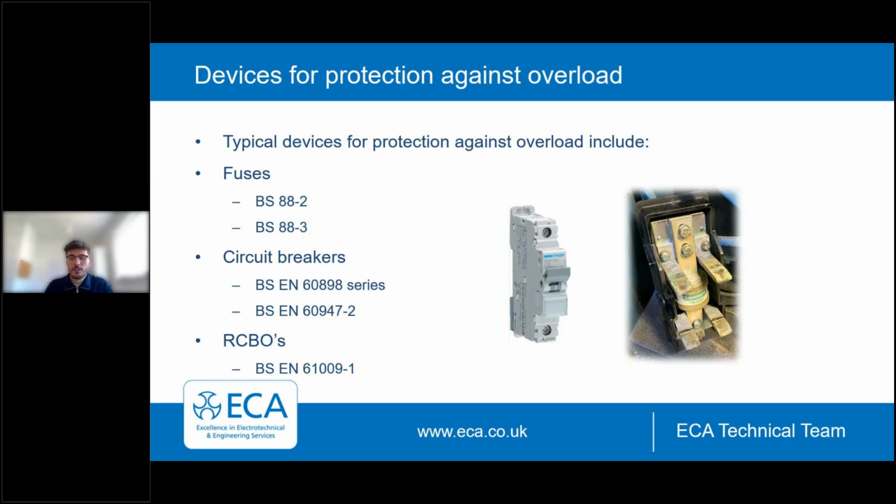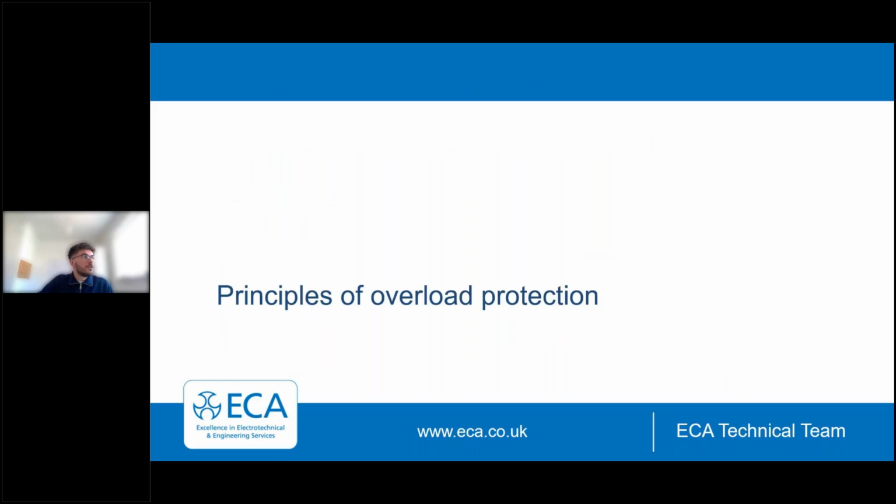Now, for some devices, particularly BS EN 60947-2 devices, some potentially being moulded case style circuit breakers, some devices are adjustable, and BS 7671 requires that they must be sealed or constructed so that alteration cannot be made without the use of a key or tool, as per the requirements of Chapter 53. So hopefully that lays the basics of what an overload is and shows some examples of typical overload protective devices that we select within installations.